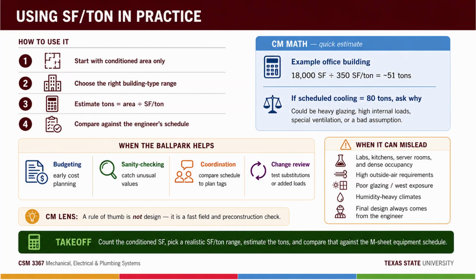For the sensible load of an airstream, Q sensible equals 1.08 times CFM times delta T. CFM is the airflow. Delta T is the temperature difference between outside and inside, and 1.08 is a constant that rolls up the density and specific heat of air. Bring in 1000 CFM on a 95-degree day with a 75-degree building. 1.08 times 1000 times 20. That's 21,600 BTUs per hour of sensible load. Nearly 2 tons, just to cool the fresh air before the sun or a single occupant does anything.